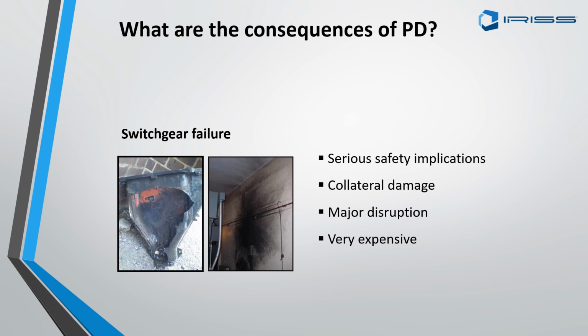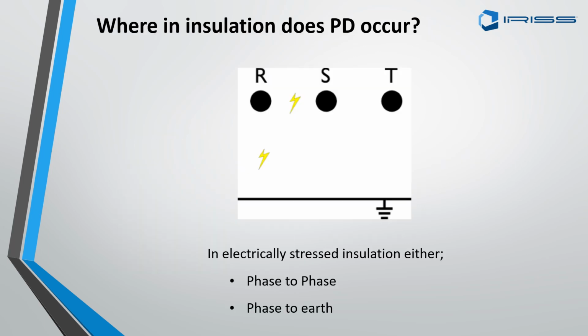I recently talked to a mining operator who had a partial discharge event that was occurring inside of a potential transformer inside some medium voltage switchgear, and it failed. The actual potential transformer failed, but it failed so catastrophically that it took them out for a number of days while they were getting replacement components and replacement switchgear in place so that they could get up and running. So this was on their primary incoming switchgear. It took out the entire facility. So you can imagine how quickly something like this can cascade into a much bigger problem.